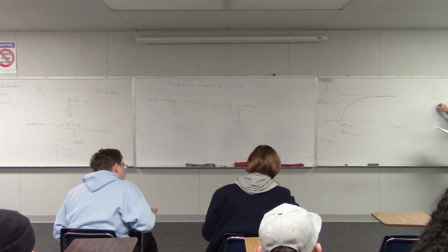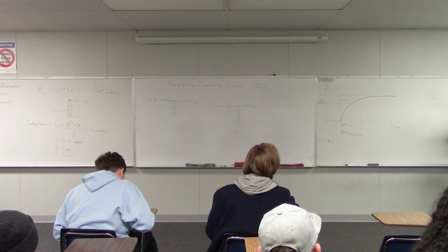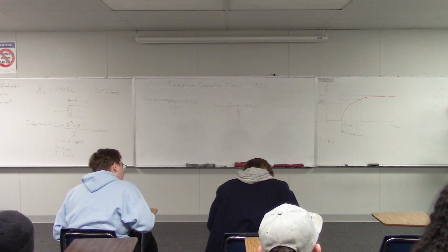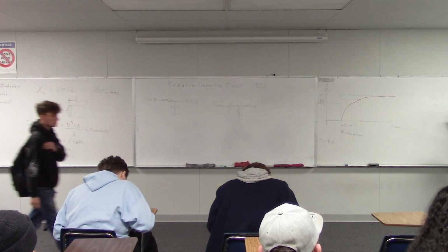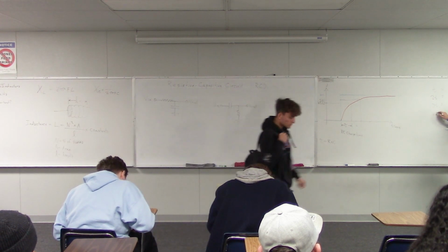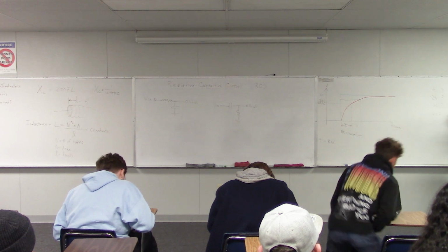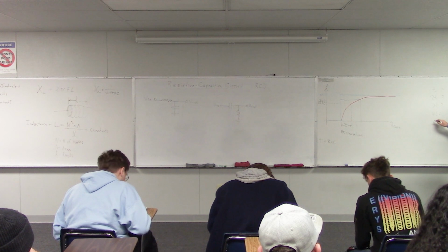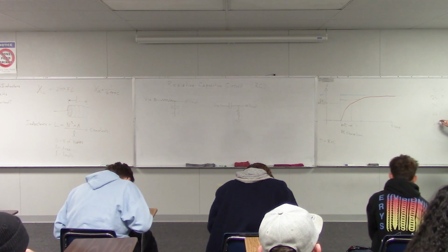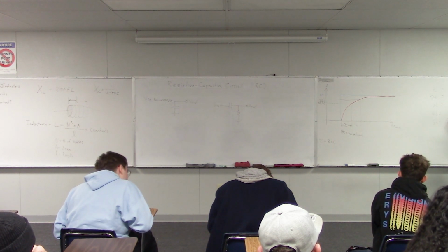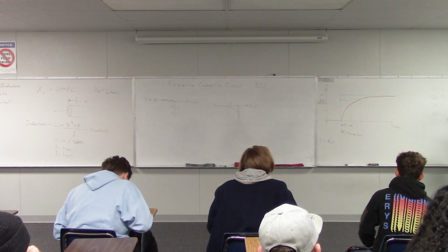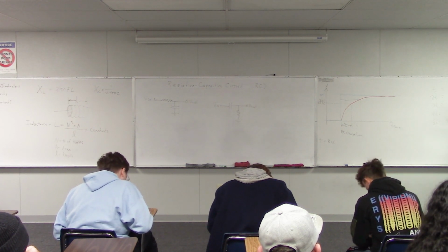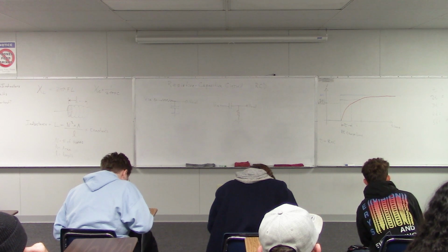After three time constants, it's up to about 95%. After four time constants, it's at about 98%. And then after 5 time constants, it's at about 99.3%. Okay?